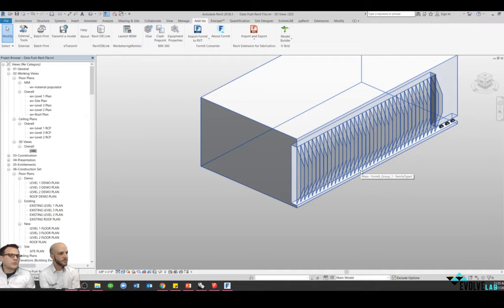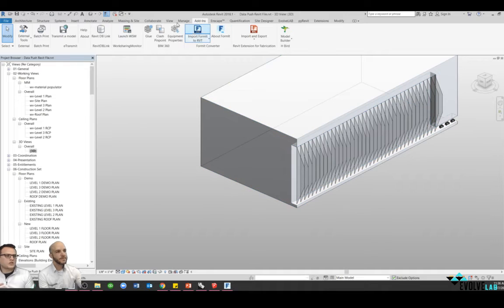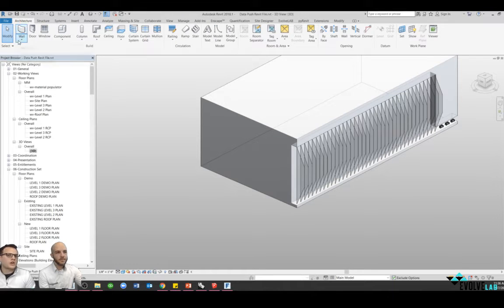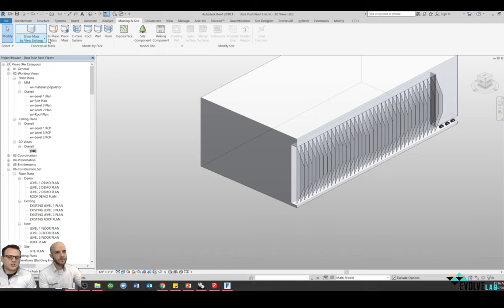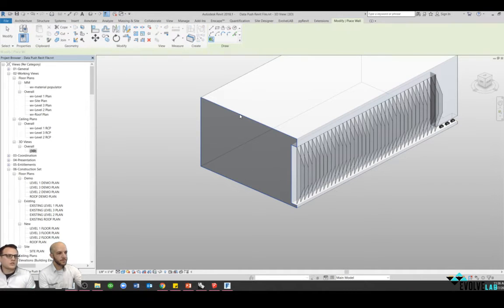The reason I don't like importing DWG files is that it loses the flexibility and the ability to change elements. Because Revit doesn't really have the ability to control layers in the same way, once you import that DWG, you lose the ability to manipulate anything in the background image. It's like working in Photoshop, where you shouldn't do anything destructive to that background JPEG or whatever sort of TIFF you might be working with.